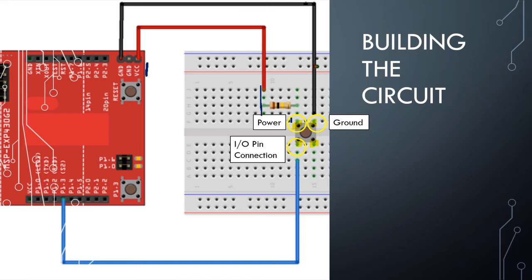And then we're also connecting a resistor as a buffer between our power source and our push button so that the current is not too high. So you're going to have your resistor, and then your resistor is going to be connected to one corner of your push button. The top right corner, you can see pretty clearly, we need to ground a corner of our push button. Quite simply, if we follow the ground wire, this just comes back into the ground pin of our board. Your board might be laid out a little bit different, but just find the pins labeled as the power source. Sometimes it will say 5 volts, and then find the one labeled as ground.